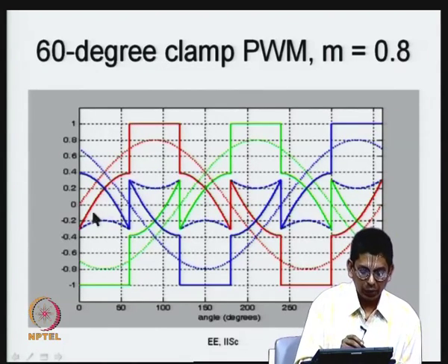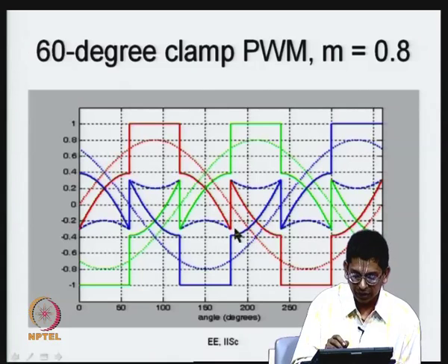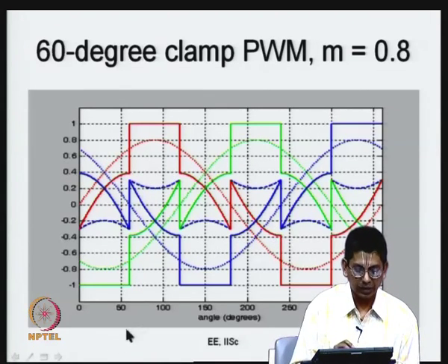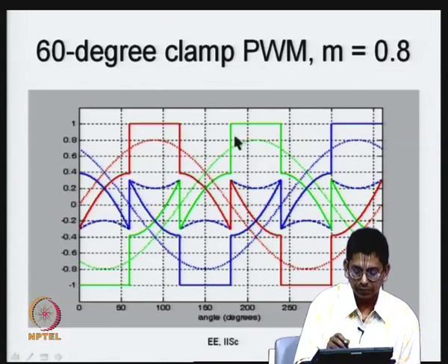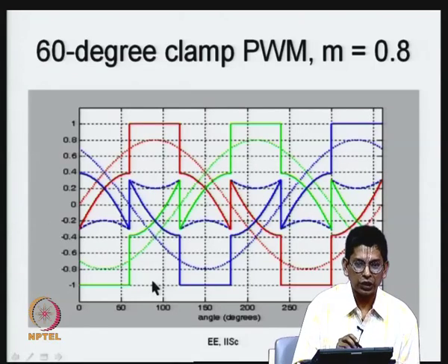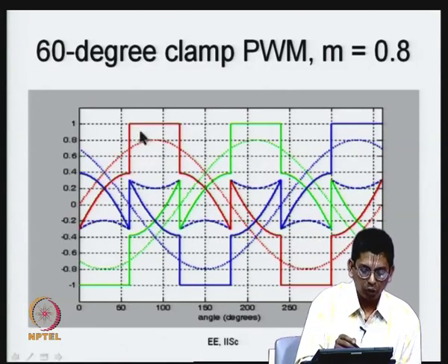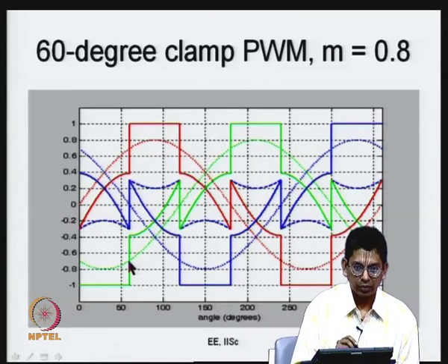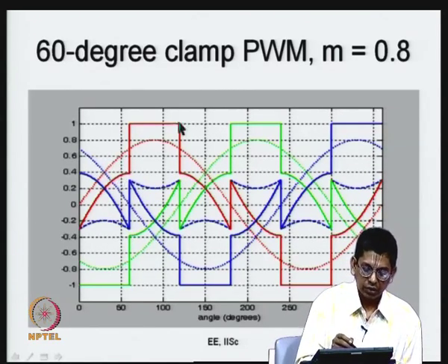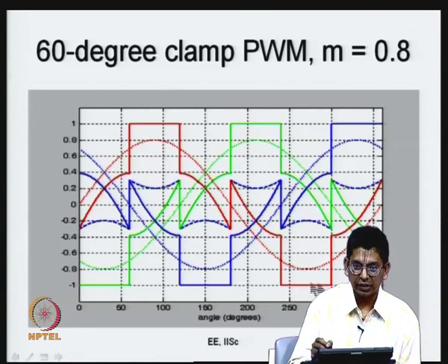Once you add, you get this resultant signal, this is your red phase signal, and your yellow phase signal is shown by the green line here. Both of them have the original sinusoid plus the common mode added. So, your red phase pole voltage, the midpoint average pole voltage measured with respect to the DC bus neutral, has this wave shape shown by the red modulating signal.